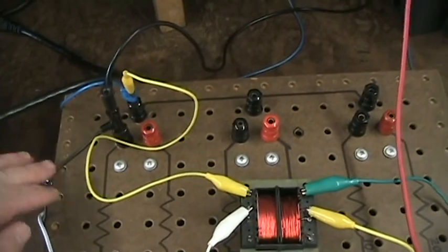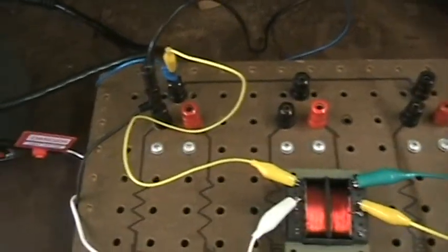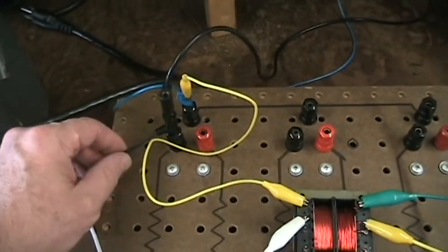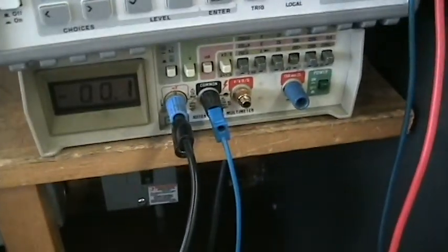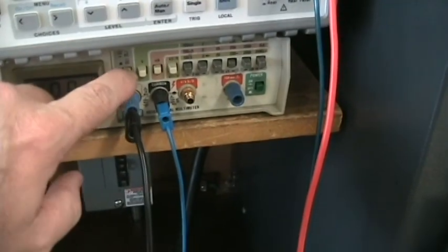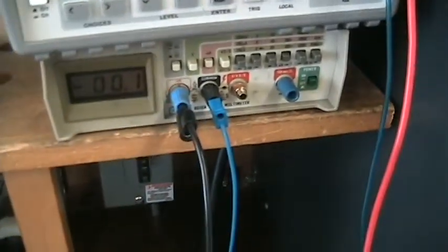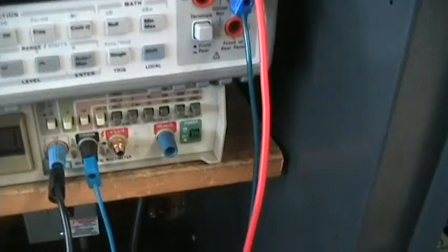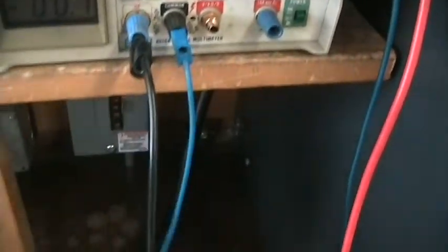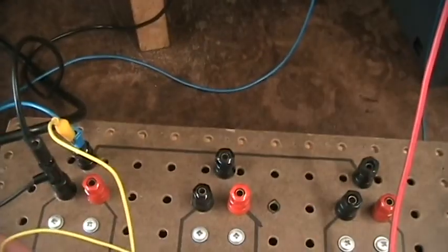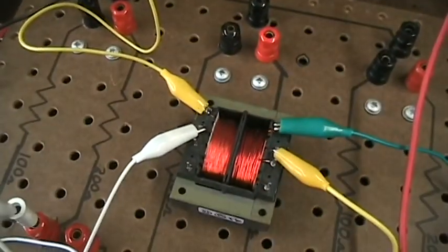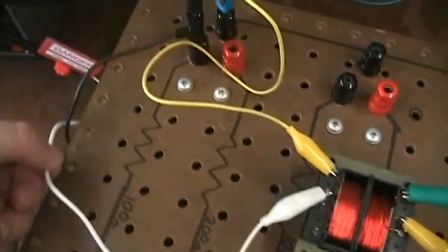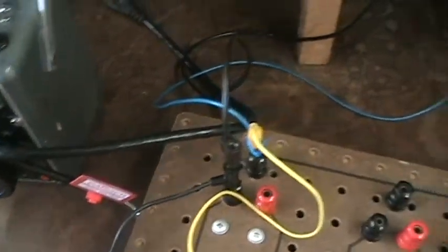We're going to take the wire from the variac, the black wire. We're going to pass it into the ammeter, and always selecting AC amps, in this case milliamps. We're going to come back from the meter using the blue wire to then go into the transformer via this yellow cable. And then the white wire will complete the circuit back to the white wire of the variac.